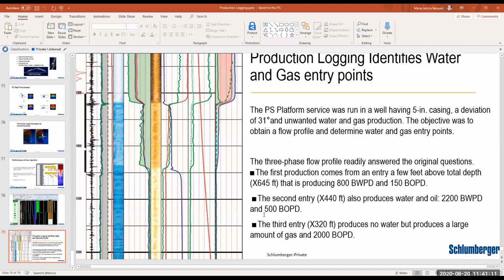First, we are going to obtain the velocity of the mix from the spinner calibration, in which we convert the rotational velocity of the spinner into a linear velocity. So the velocity of the mix is what is going to be an input to be able to calculate the velocity profile correction factor, which is going to be dependent on the Reynolds number.